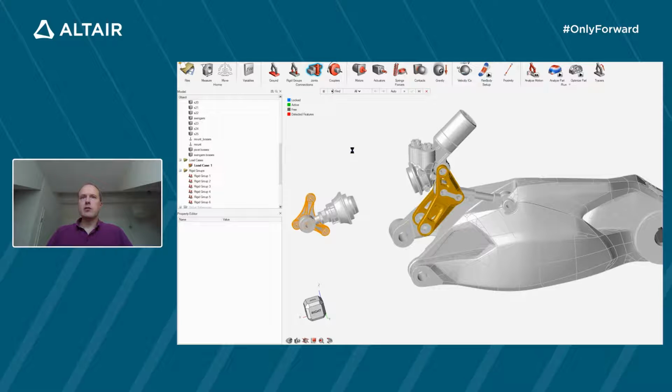Now, if I go to this joints menu, you will see there's a search algorithm which will automatically find all the different either aligned holes or the single holes in your model. And from there, you can review the holes that were found automatically and manually define or select the ones that you want to convert into, for example, a pin or ball joint.